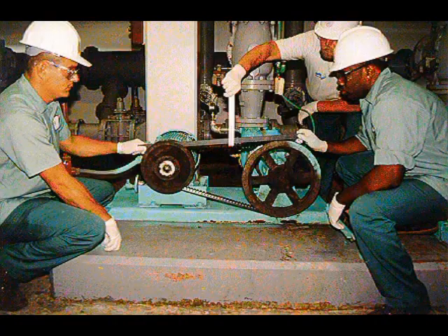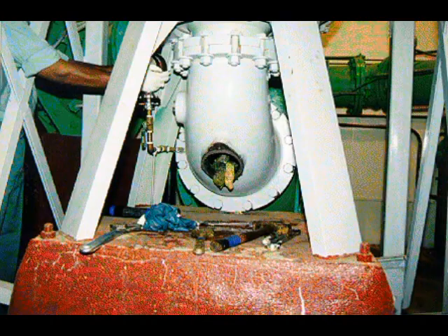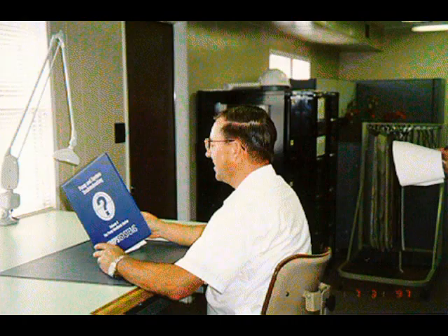An operator will also want to be able to properly maintain and replace certain components. This means that he or she will be lubricating parts that wear, checking alignment, and cleaning and repairing drivers, drives and pumps, as well as changing packing or seals, replacing impellers and wear rings, and unclogging the pump. Always refer to the manufacturer's instructions for details on operating practices that are specific to a certain manufacturer's equipment.